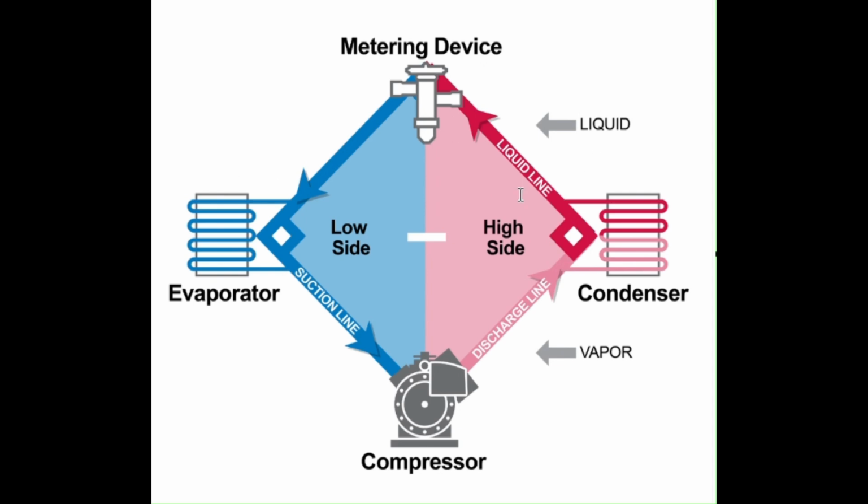So, the whole purpose of the system is to feed the evaporator with liquid refrigerant. Now, the evaporator needs liquid refrigerant because the boiling off of this liquid refrigerant is what creates the heat transfer. It's important to note that only when the liquid is boiling off in the evaporator is there a heat transfer from the surrounding areas into the refrigerant inside the evaporator. So the whole system serves this evaporator to provide it with that liquid refrigerant that it needs.